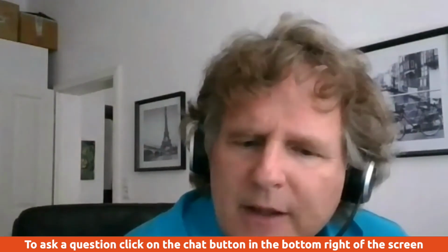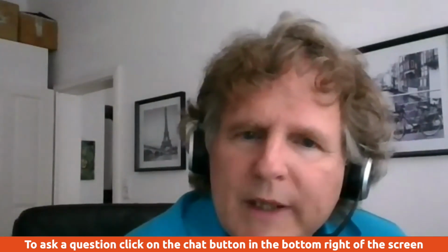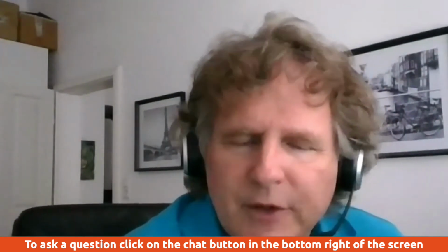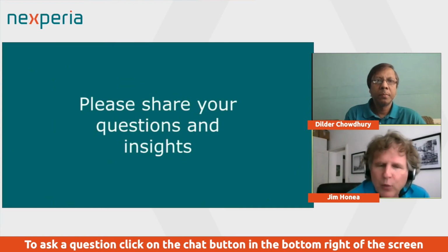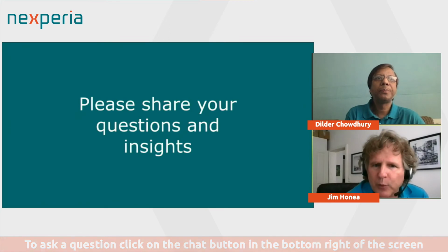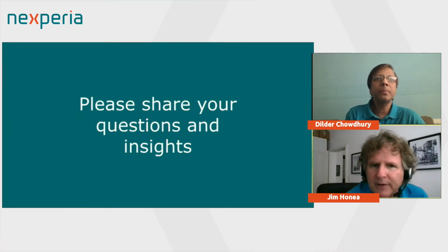And the key thing for keeping switching loss low is to achieve the desired on resistance with the minimum amount of charge, right? It's moving these charges around where you get loss, as we've been talking about. And so getting an on resistance with the absolute minimum charge is the key to having minimum loss. And that's where GaN gives an improvement over a 650-volt silicon MOSFET.